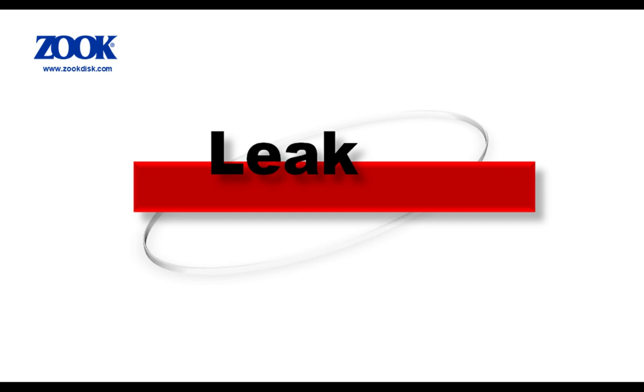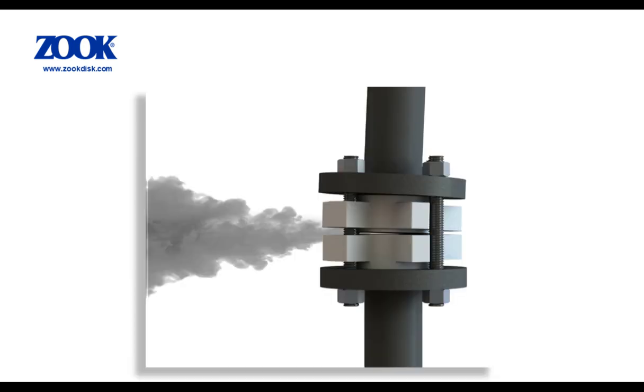Most rupture disc assemblies utilise gaskets to seal the device into the piping, so gasket style and more importantly gasket integrity is critical in ensuring a proper seal. The disc itself is normally sealed in the holder using a metal-to-metal seal, so it does not need a gasket within the holder.